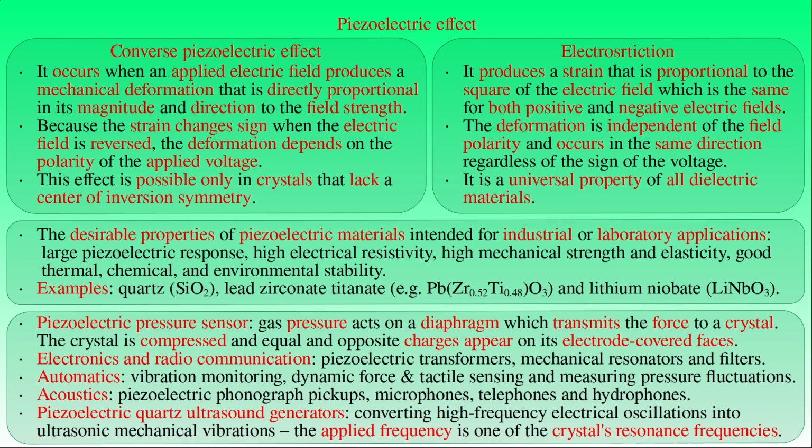These devices use the converse piezoelectric effect to convert high-frequency electrical oscillations into ultrasonic mechanical vibrations. When an alternating voltage is applied, the piezoelectric crystal expands and contracts periodically due to the converse piezoelectric effect. If the applied frequency matches one of the crystal's mechanical resonance frequencies, the vibration amplitude increases dramatically, producing intense ultrasonic waves. We finish the presentation on ferroelectricity and piezoelectricity with the discussion on pyroelectric effect and electrets.